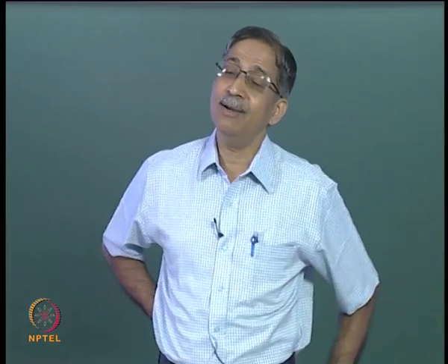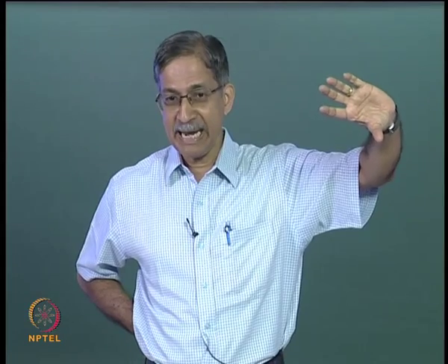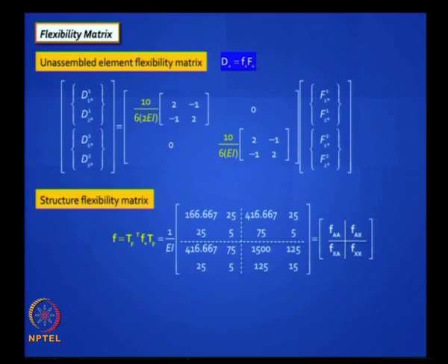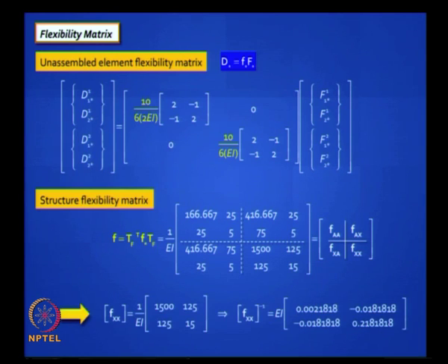Now which is the one you need to invert here? In the stiffness method we always looked at the top left hand corner, that was KAA, but in flexibility, because everything is upside down, you have to look at the bottom right hand corner, that is Fxx, is it clear? So that is 2 by 2 because your degree of static indeterminacy was 2. Take it out, invert it also, be ready. Inverting a 2 by 2 matrix is very easy. You are now ready to handle any loads.